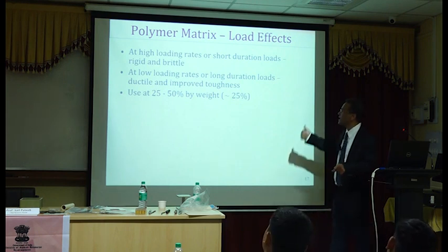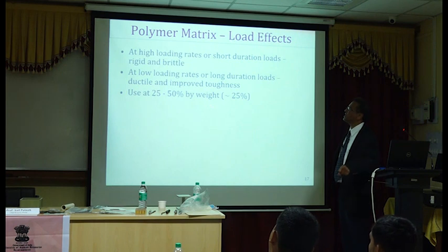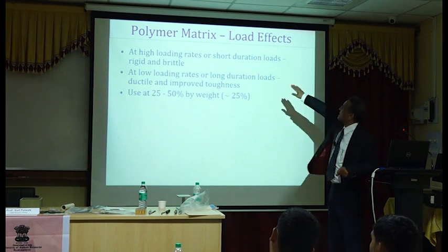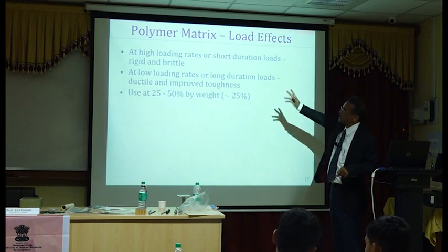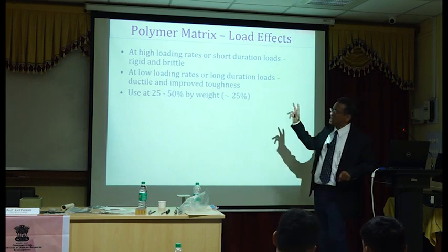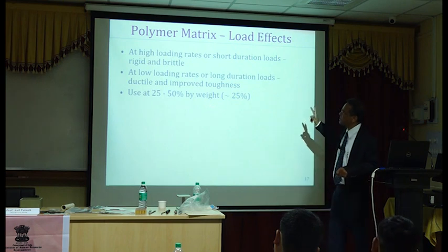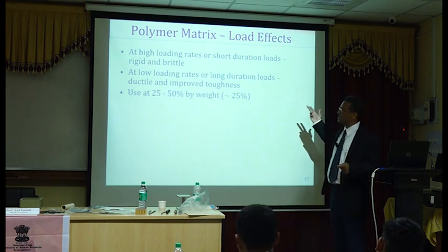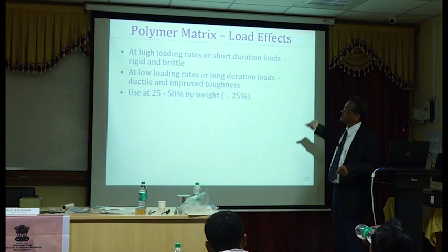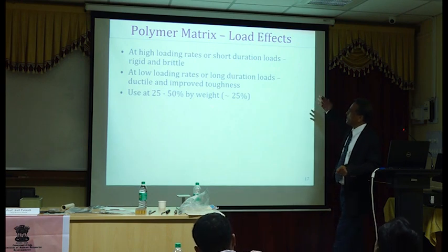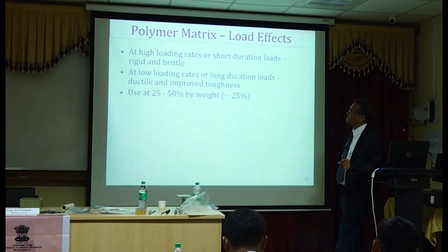But I think it will give you larger strength. I think it's the same thing here. High load rates or short duration loads. Only thing is it becomes very rigid and brittle, so that's a problem, but so is concrete. Concrete is also brittle. Long duration loads, you can have better ductility and improve toughness.